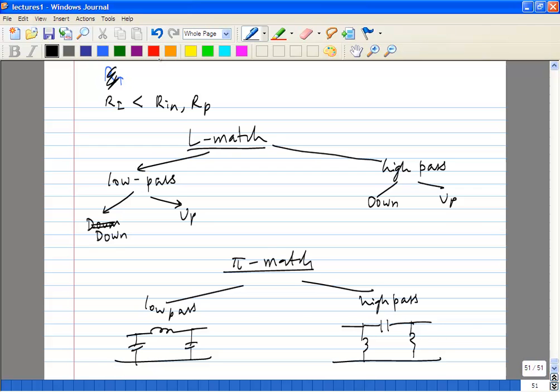A few picofarad will probably consume a few tens of square microns, whereas an inductor of a few nanohenries will occupy 500, 600 microns, a square or a circle which has a diameter that could start anywhere from 150 microns, and if you want higher Q you might want 500 microns, something like that.